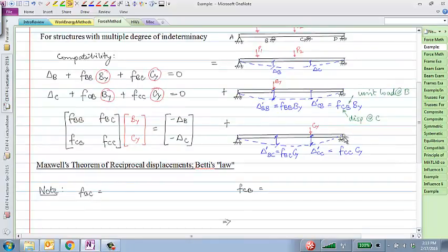That's this problem, right? So think of this Cy as a virtual load, and if I were to apply Cy as a virtual load, and to find the displacement at B, sorry, to find the displacement at B due to an actual load Cy, we would apply the virtual work method, and we would calculate the moment M due to a virtual load at B,